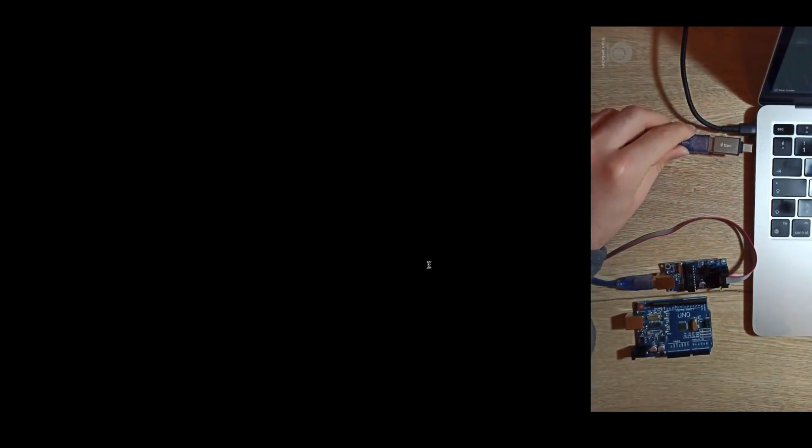I'm not going to connect it right now, but assume it's connected. And the programmer is in turn connected to a special SPI header, the 6-pin header here, like this. And the main computer talks with the programmer, and the programmer, on behalf of the computer, programs the microchip here.